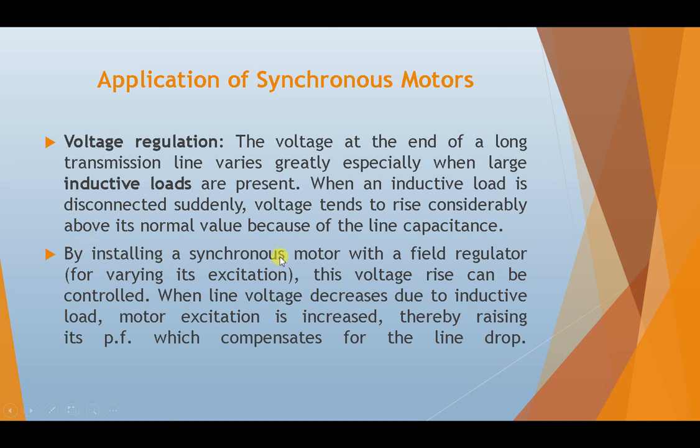By installing a synchronous motor with a field regulator for varying its excitation, we can achieve leading, lagging and normal power factor. This voltage rise can be controlled.